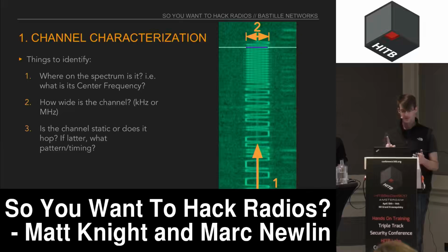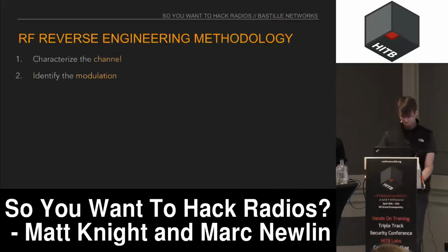We're looking for what is its center frequency, what is the middle of the channel. We're looking to establish how wide the channel is, how much spectrum the signal traverses. And finally, we're looking to establish whether or not it's a static channel or whether there are multiple channels and the signal hops around. So those are really the 3 things that come to defining the channel.